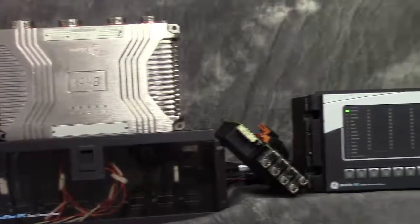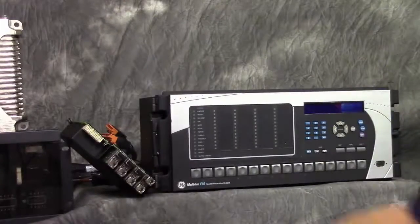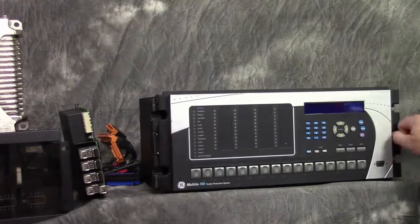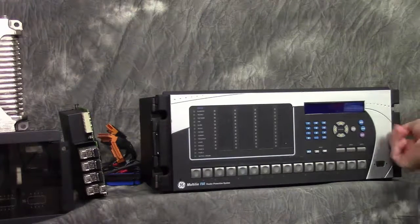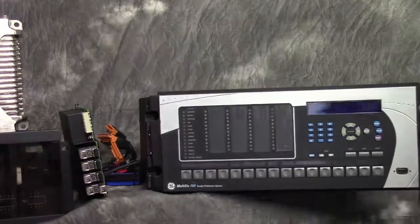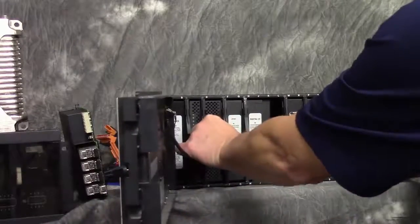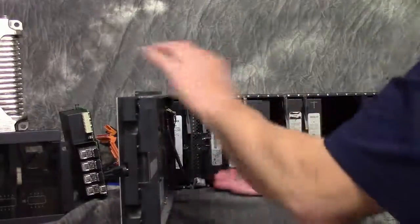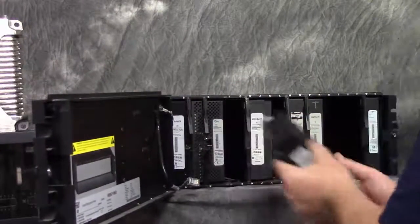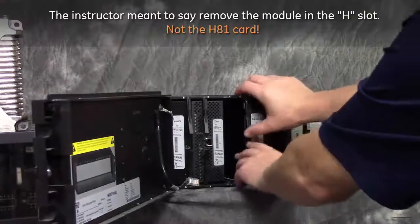So the first thing that we need to do is power down the relay. With the relay powered down, we're going to go ahead and remove the F card and the H card. Now the reason we're removing these other cards is because the brick takes the place of the DSP card. So what we're going to do here is remove the card in F slot. Let's put it off to the side. And we'll take out the H81 card.